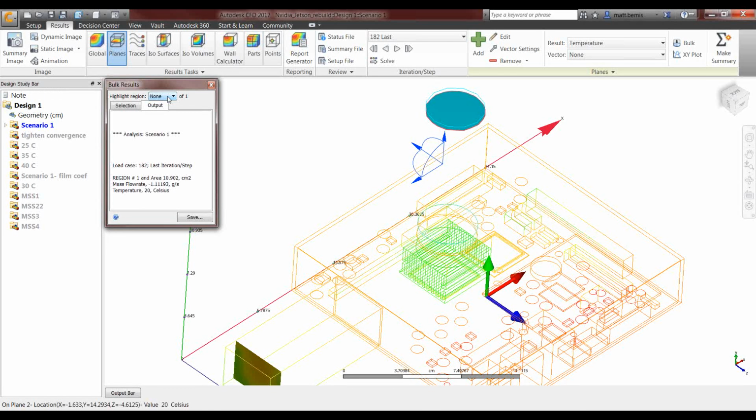If you've tried all else and you're convinced that this is a solvable problem because you have two different completely separate fluid domains, probably not a bad idea to reach out and ask for some help. Yeah, I see what you're saying. So since there's no pressure reference inside the sealed box, is it going to have a hard time honing in on the correct pressure? Right. Yeah. So what you do there by assigning a zero pressure, just give it a reference at a solid that's then going to be interfering with the flow or the pressure distribution.